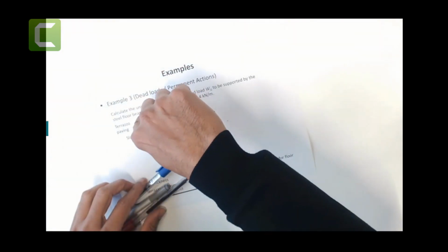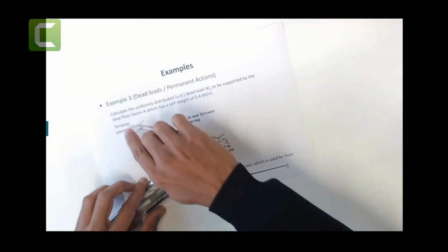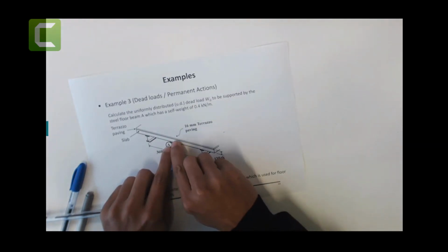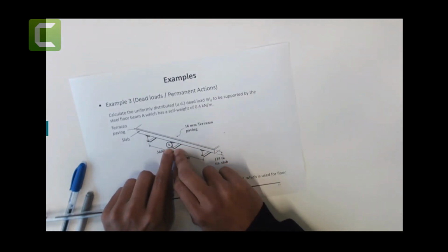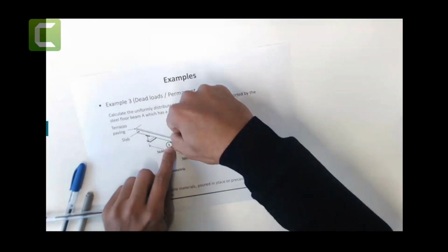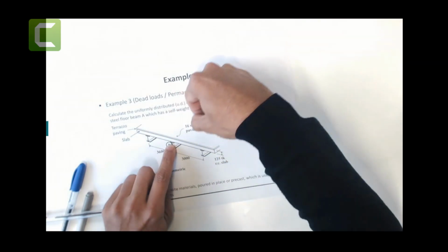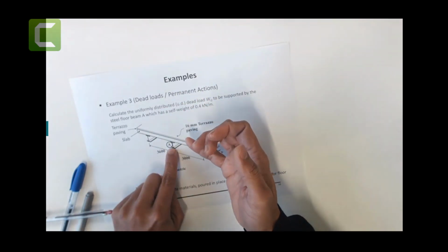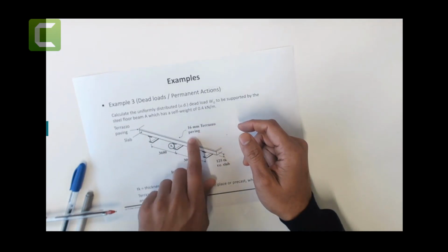So these are carrying some kind of a thick 16 millimeters terrazzo paving. So these beams need to carry their own weight, right? And by the way, they will apply the UDL load, line load, kilonewton per meter on this beam. So this beam needs to carry its own weight. Then it needs to carry this slab that is going to come on it, and then it needs to carry this terrazzo paving. So it needs to carry 3 different loads. Number 1, its own weight. Number 2 is the slab. Number 3, it needs to carry this terrazzo paving.